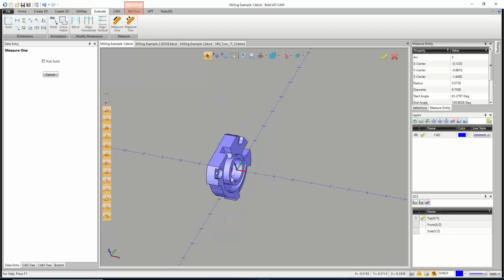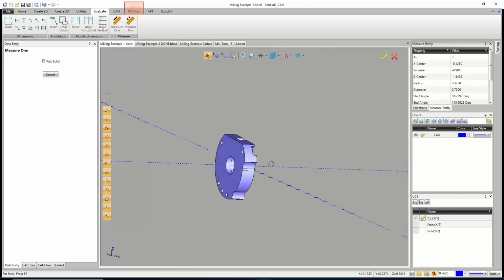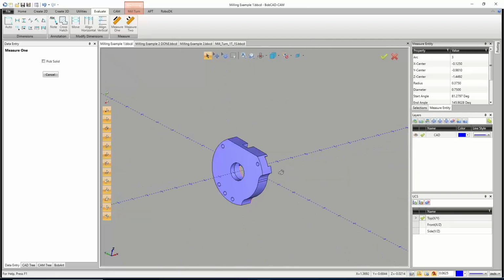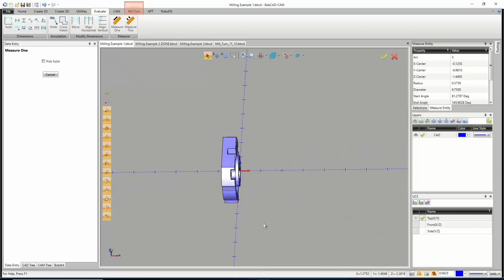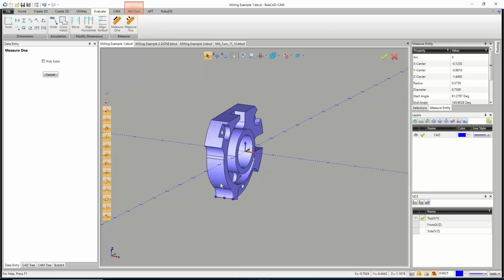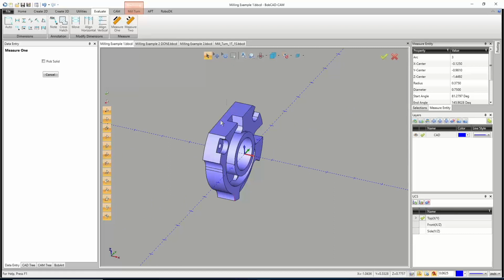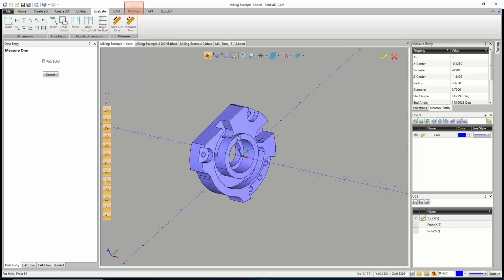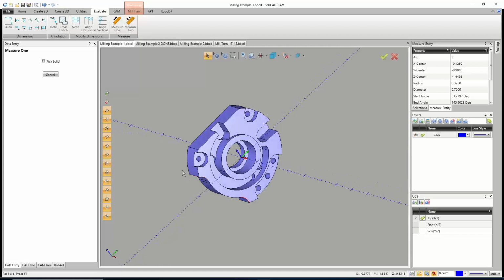You've got to think, with this side here, our part's not too thick. It's under an inch wide, probably about 3/4 of an inch wide or so. So I could come in with a tool from the front face and machine these flats and these little areas on the side, and that's what I planned on doing. But like this flat here, you could technically have a tool that comes in like a cross mill and machines that flat using the tip of the tool instead of the side of the tool. That is an option, but the way I see it, if I'm already going to be doing this curved side here, might as well just do the rest of it.